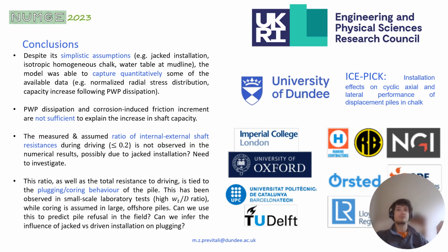So, conclusions: despite the very simplistic assumptions we adopted, the model was able to capture quantitatively some of the available field data, such as normalized radial stress distribution and capacity increase following pore water pressure dissipation. This pore water pressure dissipation and the corrosion by itself is not enough to explain the significant pile capacity after setup.